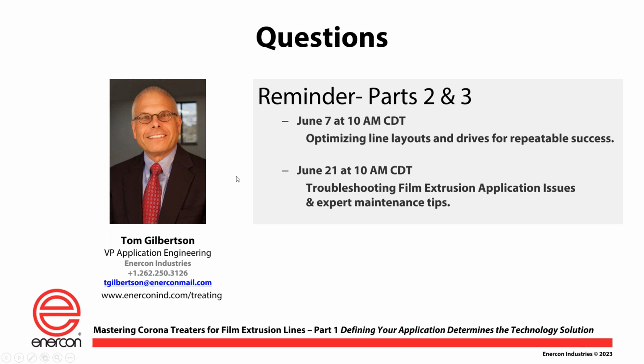If I run different films that respond differently to Corona, what is the operating range of a Corona treater? How much can it vary? Great question. Most modern day Corona treaters have a pretty wide operating range. So for example, let's say you have a 1 kilowatt or a 1,000 watt power supply. Well, that power supply can easily run down to 100 watts, maybe even less.